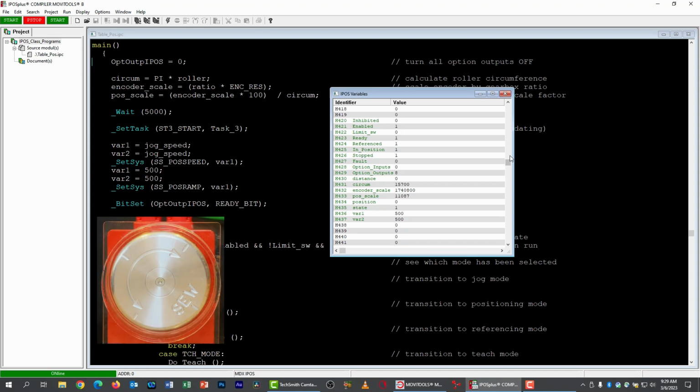That is the jog state. So let's try to jog. I'll go ahead and turn one of the jog bits on. We'll turn on DI13, and the motor is rotating counterclockwise. All right, turn DI13 off, drive stops. Let's try DI14, and we've got clockwise rotation, so that works.